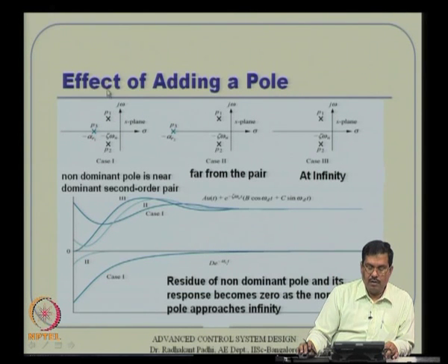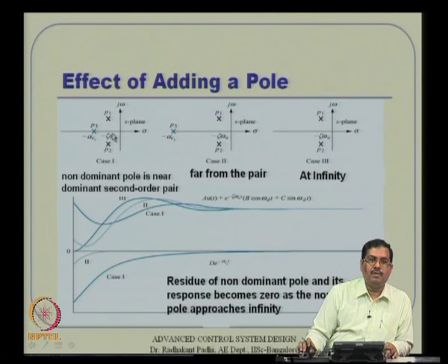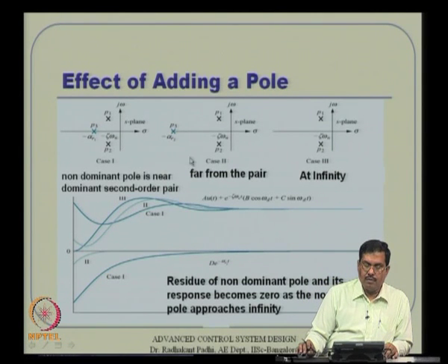Okay. This is actually like a third order system. The second order approximation is not good here, whereas this is kind of okay depending on your application, and this is a perfect second order system. So, the message here is the third pole should not lie close to the dominant second order pole. If it lies close, then the approximate second order system will not hold good actually.